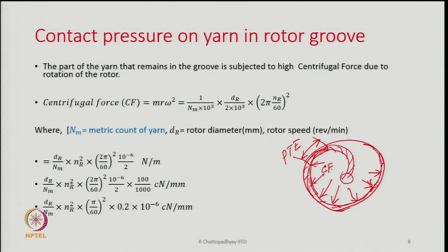So, why do we need to know the pressure? If the pressure is too much, the yarn is rotating on its own axis, and this torque may not be able to flow into the band of fibers, because the band is resting against the rotor wall, in a place which looks conical in nature, and then if we want to drive the torque, we have to overcome the frictional resistance